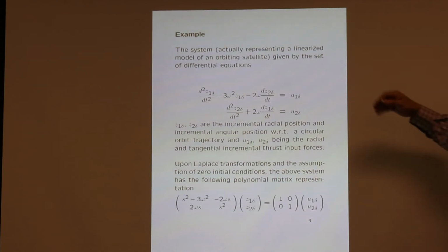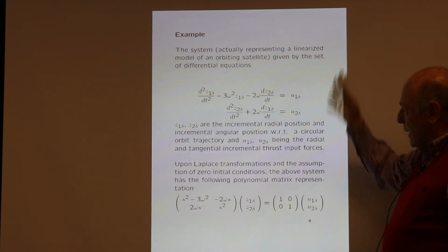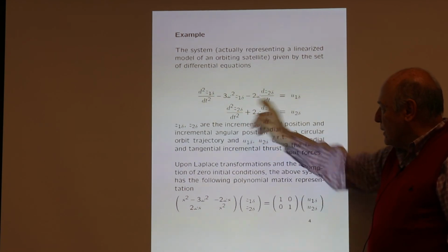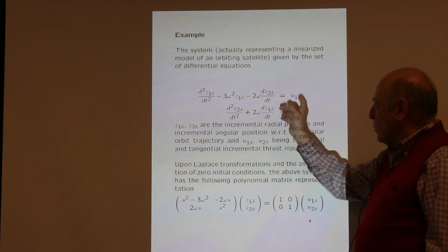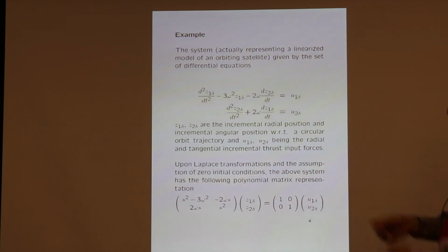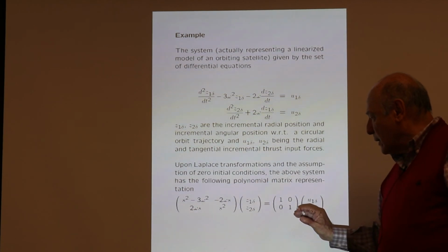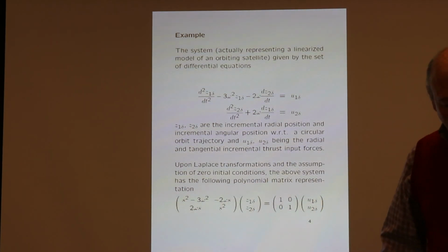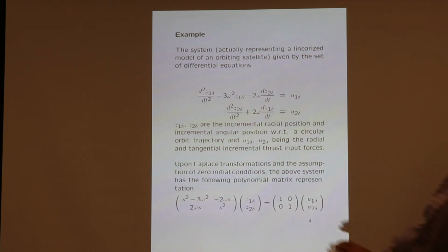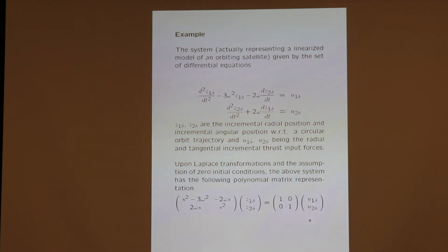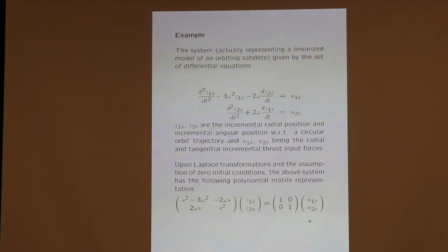But this system is controllable. In some sense it's very easy to see from here, intuitively, that the system is controllable. The highest derivative of C2 is being controlled by U2, and the highest derivative of C1 is controlled by U1, and the rest is interaction between the states. So in some sense, the possibility of inverting this matrix will be crucial, and the possibilities of having no common factors between these two matrices, and we will have to be precise about what we mean by those common factors.